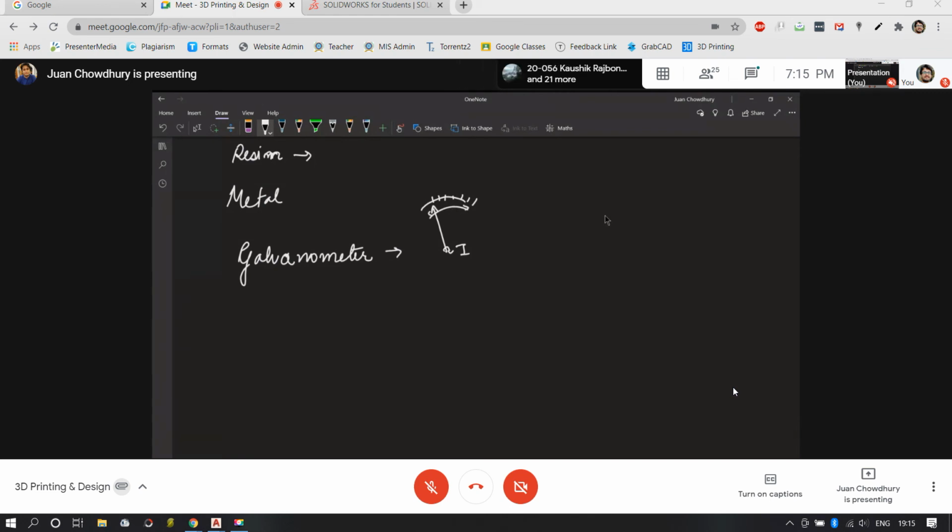That was evident. If you remember, the galvanometer readings were not very stable. They used to flicker to a great extent, right? Then we have to tone it down. So if we really want high sensitivity, instead of this needle, on the axis of the galvanometer I'll place a small mirror.